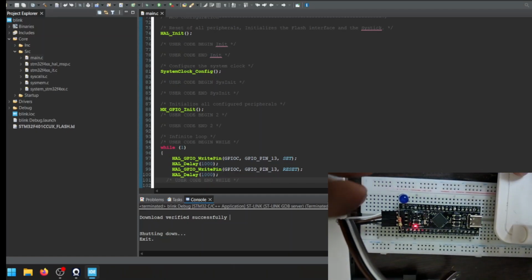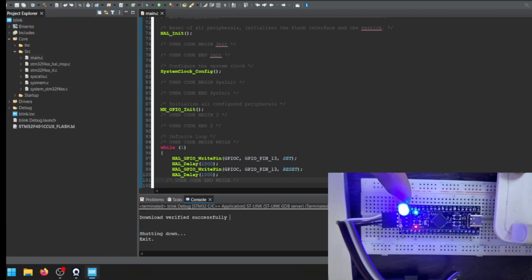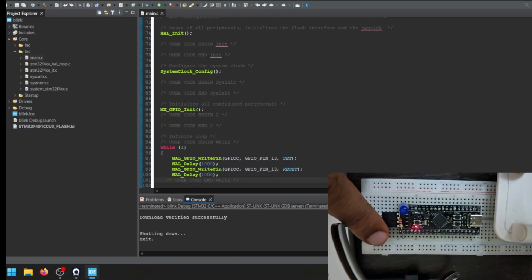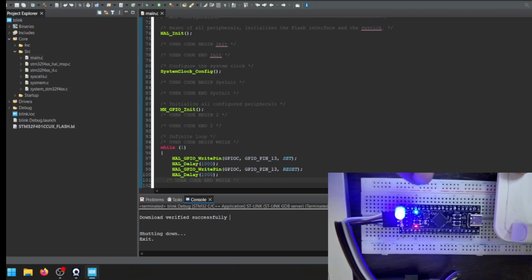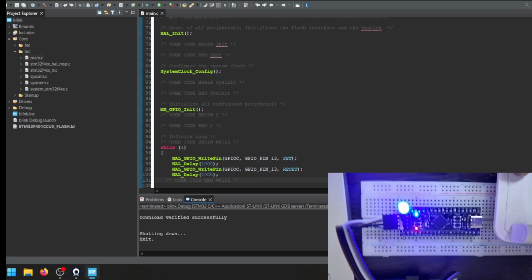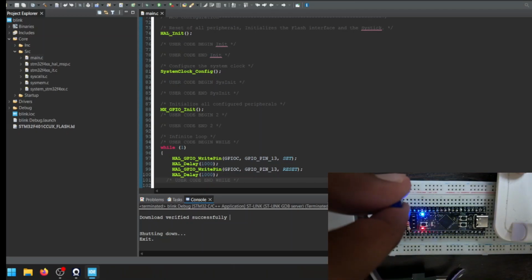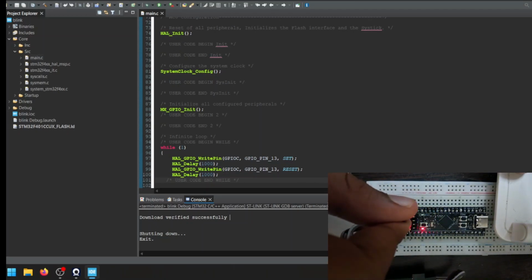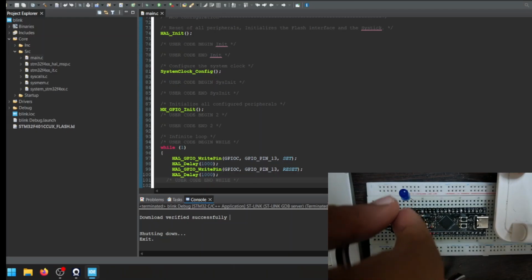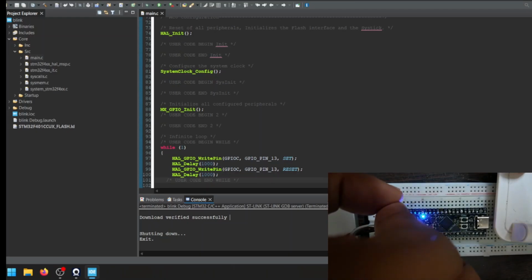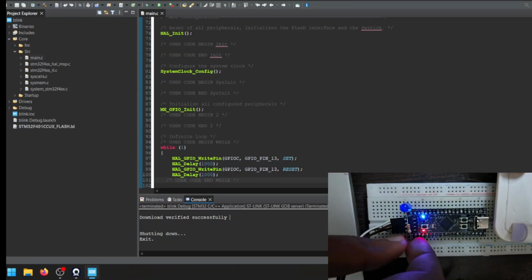so what we did here is we switched the polarities of the LED and we connected the resistor to the 3.3 volts. And now both of these LEDs are blinking in sync. They are blinking together at the same time. And if I just invert this LED, connect the anode to the C13 pin and the cathode and this resistor to the ground, then they started blinking alternatively.